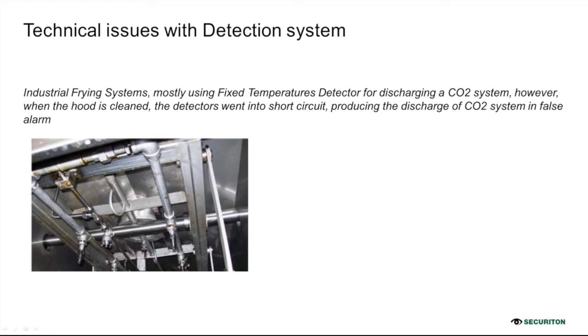Any discharge of CO2 puts a lot of other routines in place. A cleaning shall be done to the entire system. That's downtime, and it causes a lot of risk factors, which means the operation will be halted. At the same time, restructuring the whole thing, cleaning up the entire system, and putting the CO2 back in place will take time. So this is not an easy operation. A false alarm is a serious risk in terms of downtime.